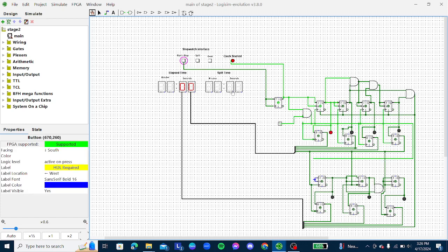To ensure the seconds display over here, I used an AND gate, which takes two inputs, one from the toggle flip-flop and another from the clock. In this case, the toggle flip-flop works as the control bit and controls the flow of the clock.